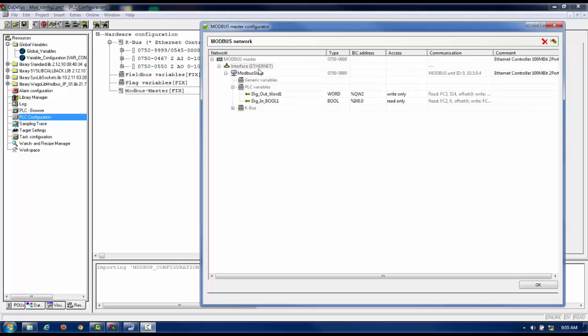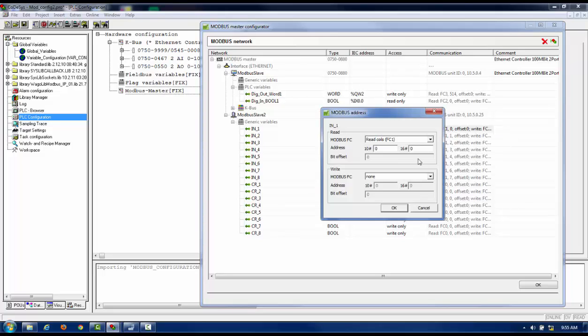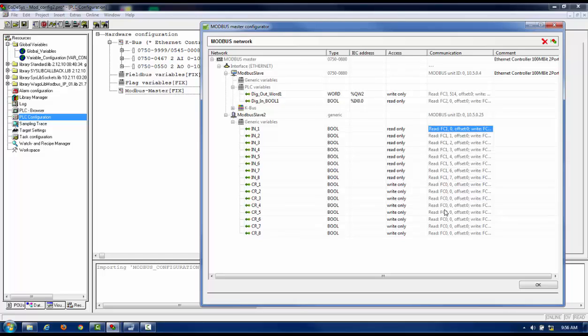So for example, in here, when I had the Speedway device and I just wanted to add it to this configuration by copy and pasting, then I can come in here and I can actually edit the information with regards to whether I want to read registers, coils, inputs, discrete inputs, single coil here on the right side, register, multiple coils, multiple registers, and so forth. So yeah, you can do additional stuff in here with regards to configuration.